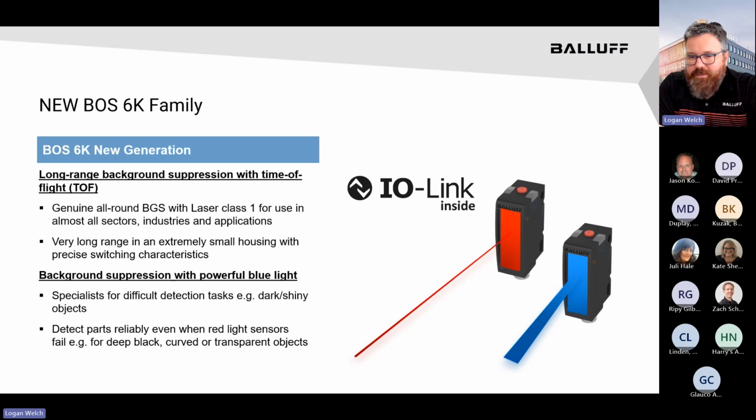Now, another way to do this measurement with light is to bounce off the object and have it come back at an angle. Well, that really limits your range, because you would have to have receivers lined up in a row, and depending on which receiver it tripped was the angle of the light that came back. So it really minimizes your range and your accuracy. This technology ups the accuracy, ups the range, and gives you a pinpoint style light output for great alignment. Great technology. So again, when you hear TOF or time of flight, that's the difference. It's using math to calculate the distance instead of an angle.